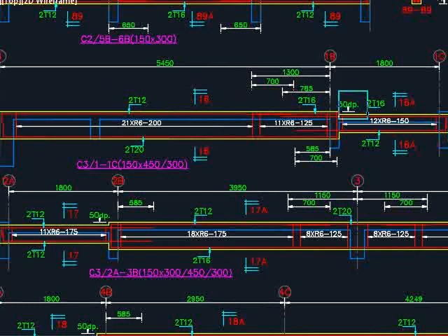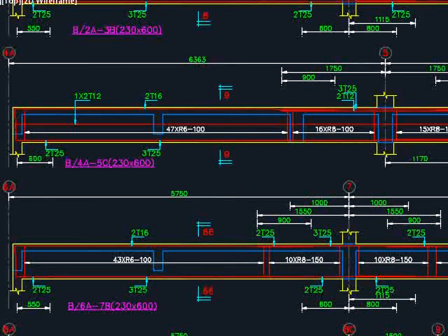And because of the drop of the member and because of the smaller size of the beam, there will be reinforcement bar embedded inside the member. You know that the reinforcement bar performs the best when it is in a straight line. Therefore, it will be good for you if you have sufficient embedded length. Then you can put the reinforcement bar in a straight line. Indicate the exact locations where you can have the reinforcement bar being cut. Next, let us try another example here.